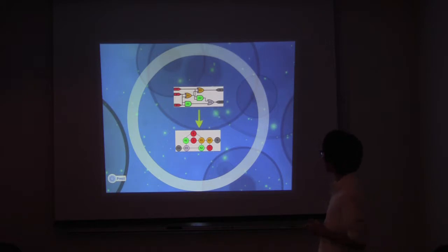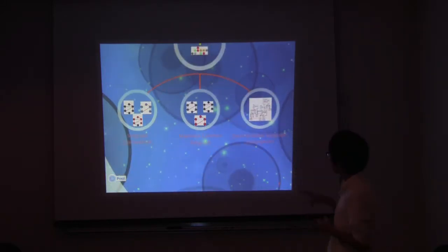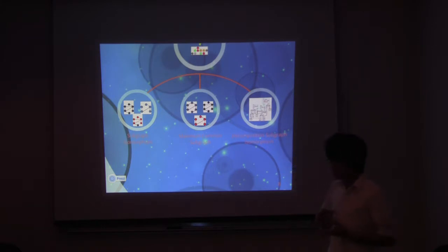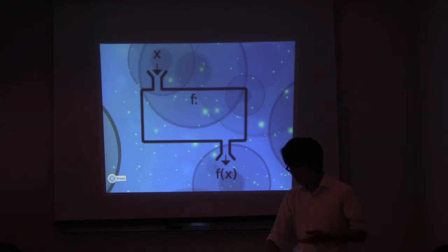Right, so after the graphical representation of the circuit has been extracted, we can then apply a wide range of graph matching algorithms in order to compare the structure of the 2 circuits. However, comparing the structure of 2 circuits doesn't necessarily describe how the 2 circuits function. On the other hand, we would have to compare the function of the 2 circuits.